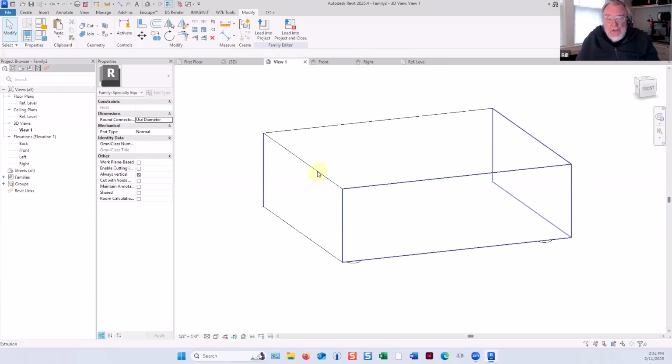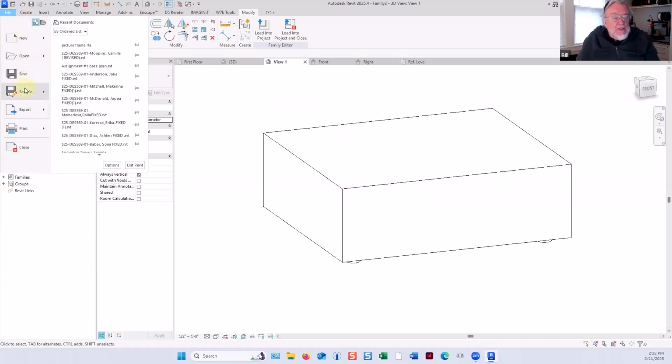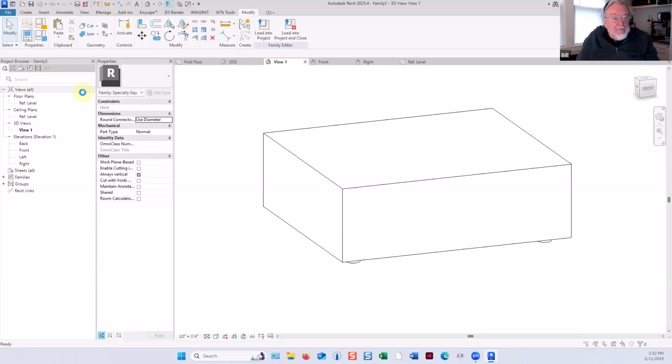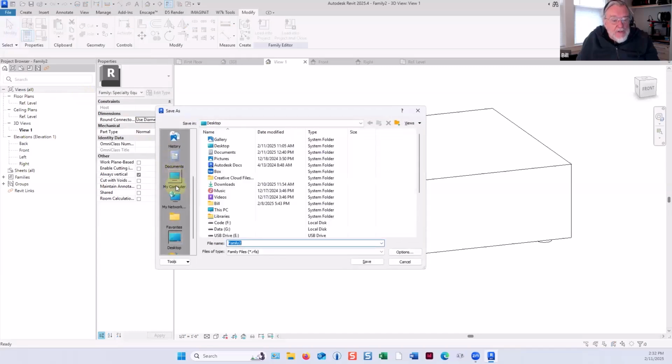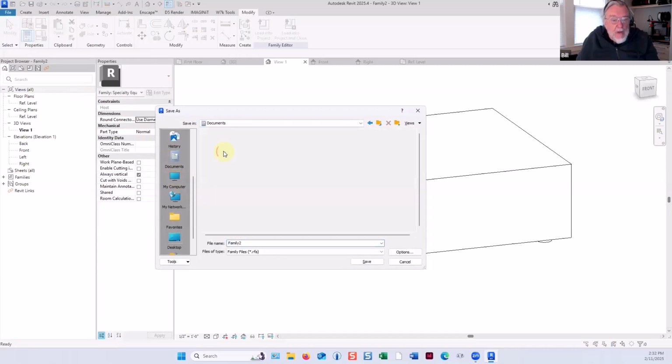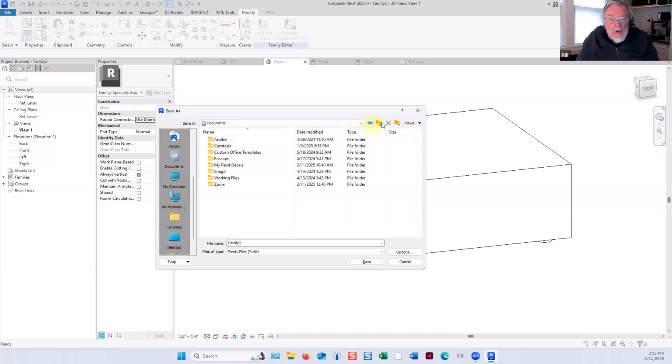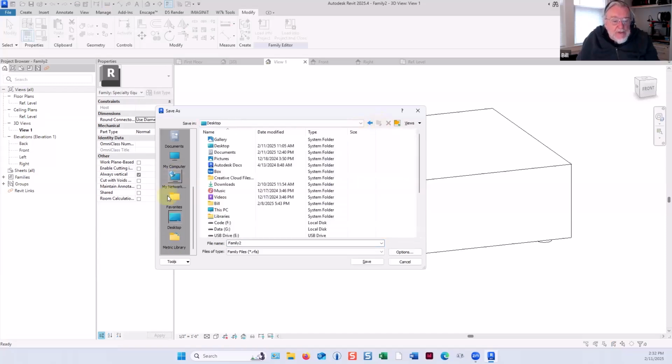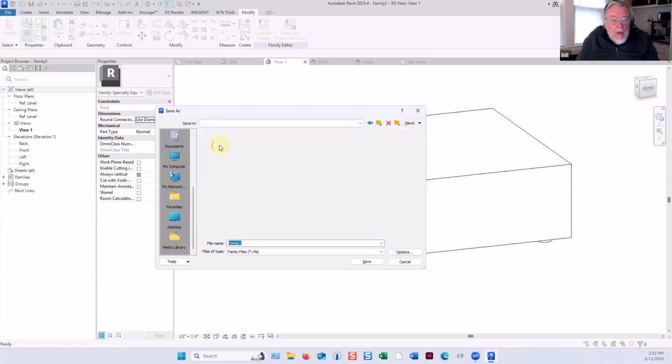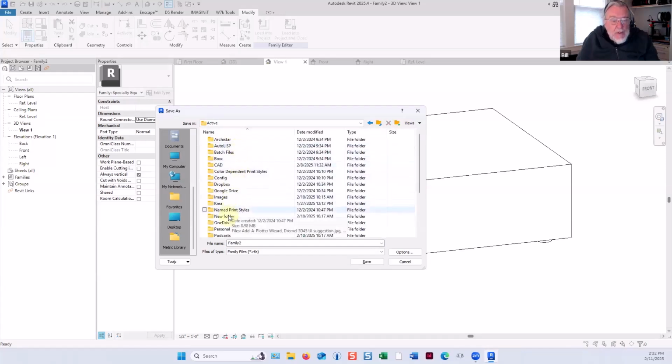We'll assign the material to it out in the project. We'll apply the image to it out in the project, and we're not going to worry about actual 3D buttons on it. With a better picture, that could have been done. Okay, so File, Save As, Family. I have mine in a different place, but you guys should be sticking this into my Revit families.